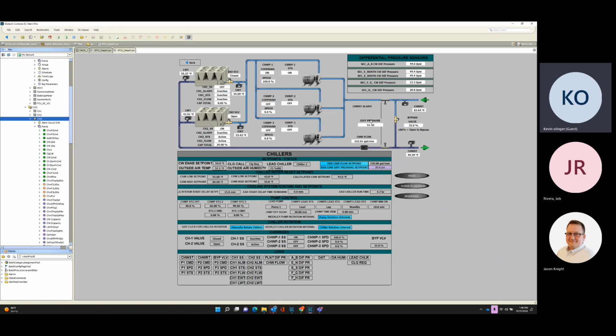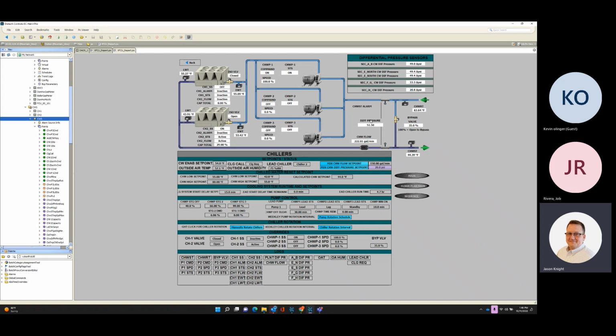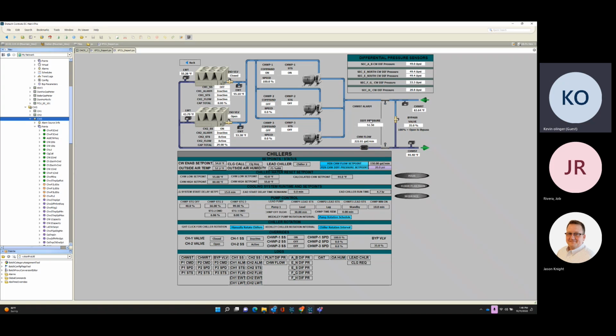From what you're saying, no wonder we're having flow problems. It makes it very hard to control. I'm 99% sure there's one three-way valve. Wow. Yeah, that right there is why we're battling and having to use a bypass, I can tell you.